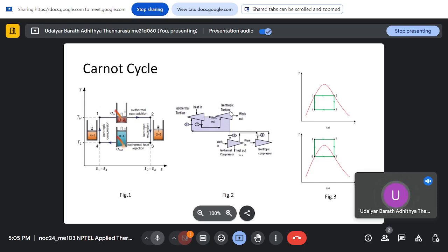And then to have an actual cycle, we said this isothermal process can be obtained when we use a pure fluid, and when we are putting it inside a two-phase dome. That isobaric process is equivalent to an isothermal process in this case, because for a pure fluid, when there's a phase change, it happens at a constant temperature. Then we said your isentropic process, which is happening as 1 to 4 or 2 to 3, is happening in a two-phase region.